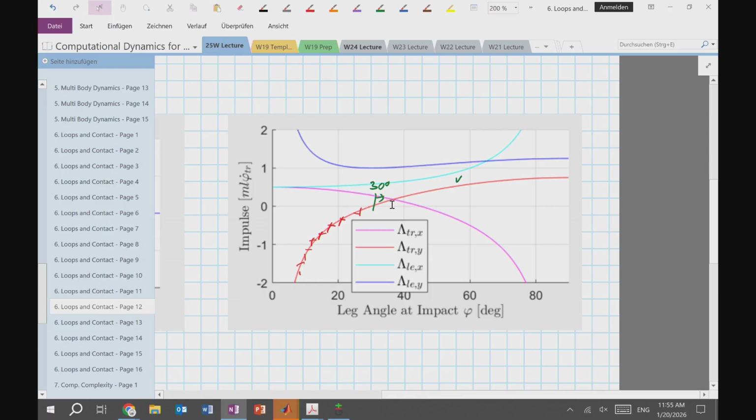If I assume a coefficient of friction of 1, I can look at this and start thinking about when this thing will start to slide, right? It will slide when the horizontal force, or impulse, it's the same thing, is equal to the vertical. Normal force equals horizontal force. That's the critical point for a coefficient of friction of 1. And this will happen already here, right?